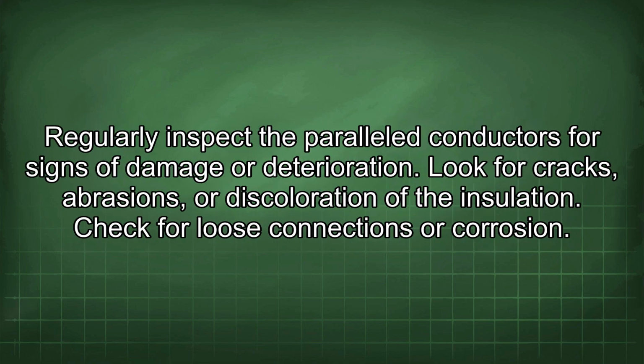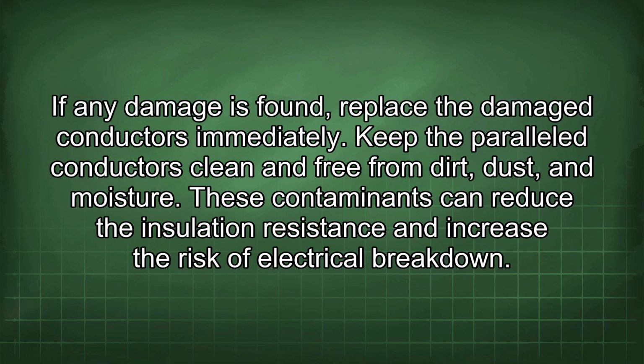Regularly inspect the paralleled conductors for signs of damage or deterioration. Look for cracks, abrasions, or discoloration of the insulation. Check for loose connections or corrosion. If any damage is found, replace the damaged conductors immediately.